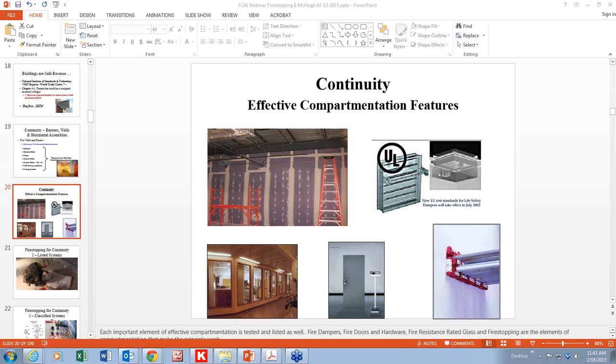The next question that came in is, let's see, two questions that came in on the text. If there's a need to provide a sleeve for future use, is there an arrangement where a metal cap is placed on both ends or a certain minimum length of sleeve extending beyond both sides of the wall? Good question on the metal cap on both ends. I don't know the answer about the metal cap thing. I imagine that might hurt the T rating if there's one required. A Firestop product could be used in a blank opening to provide a fire resistance rating. It might be easier to mess with and easier to take off and put a new penetrating item through at a later date. Would it be on both sides of the wall? It'd be wherever that Firestop system for the blank hole allows.